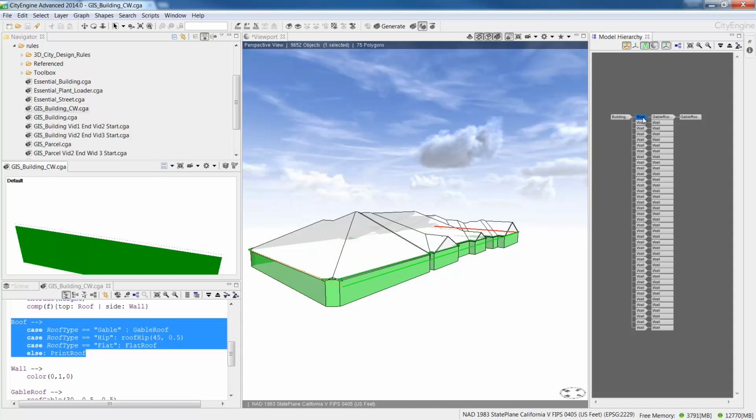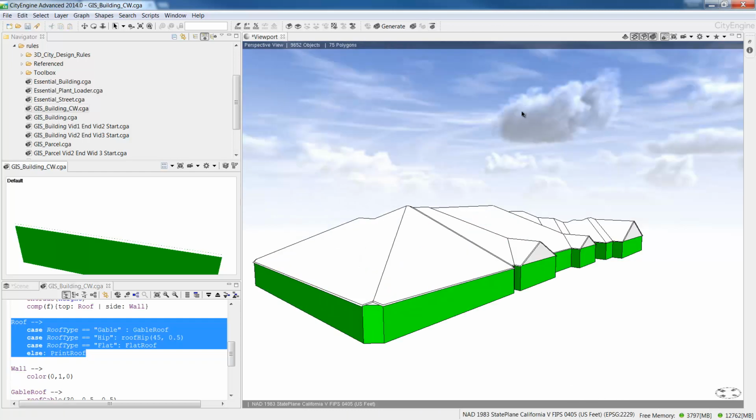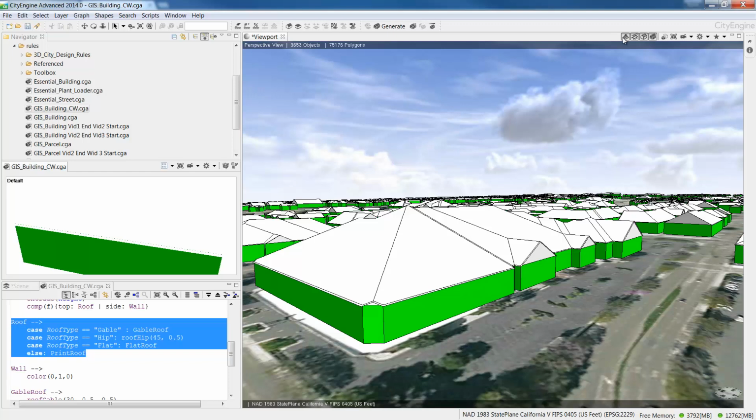Note that the scope shown for the roof rule is for the shape entering the rule, not the shapes exiting the rule. So for the roof rule, you'll see the scope of the single top face of the previously extruded 3D volume. This one has an XY scope with green and red axes shown, and the blue Z axis is not shown. Also note that all faces generated from extrusions have an XY scope. Before proceeding, turn off the Inspect Model mode by toggling the button on the toolbar.